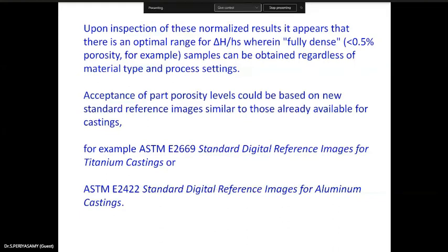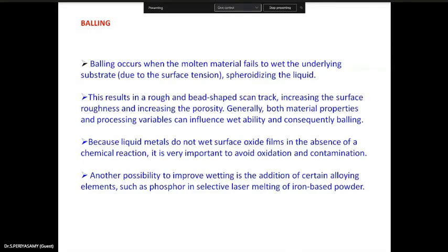Then one will be overlapping with another, and you have a non-uniform gap between the 4 particles and the next 4 particles. In that case also you have a difference between one segment part and another. So these things influence the hatch spacing, the center to center distance between melt pools in the build plane.